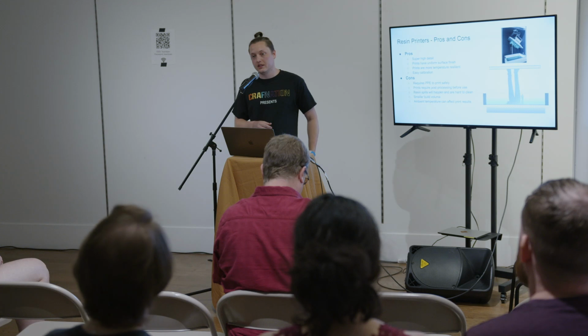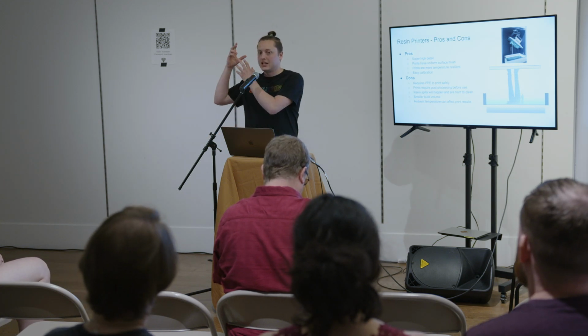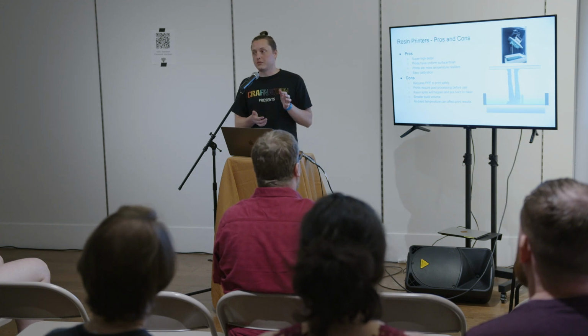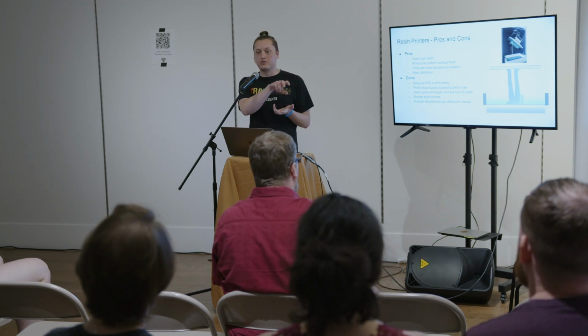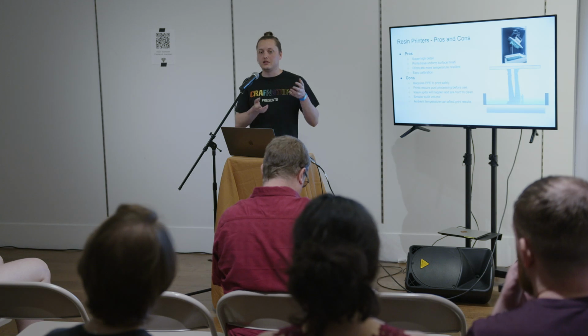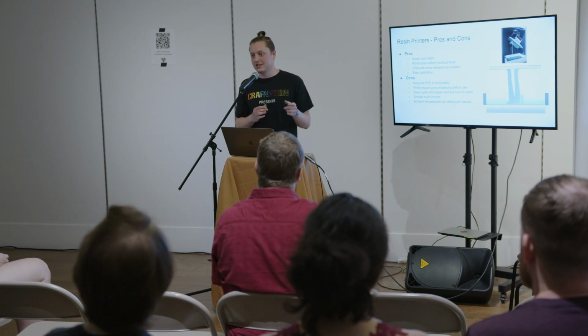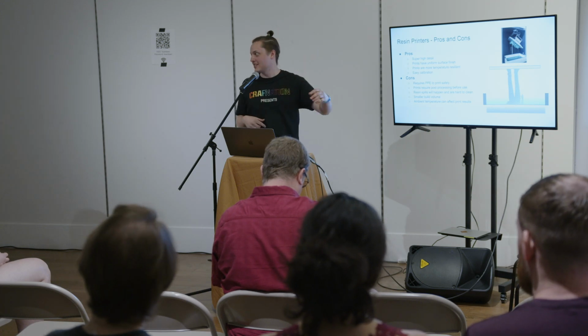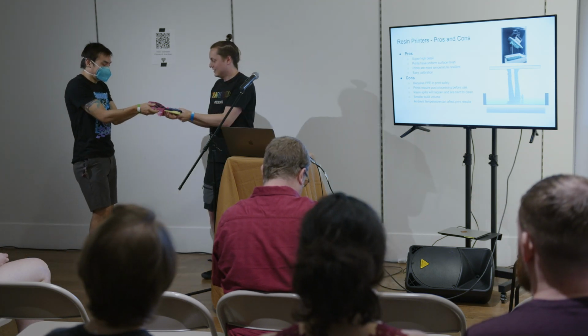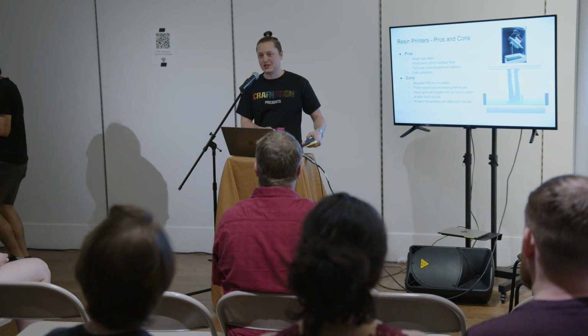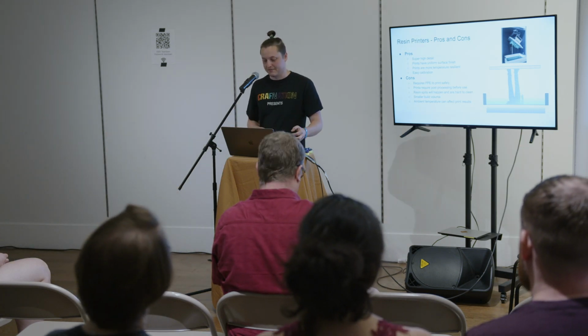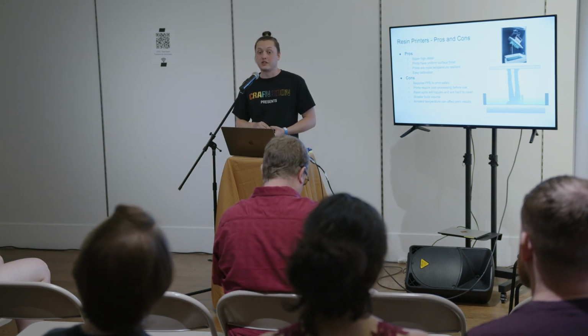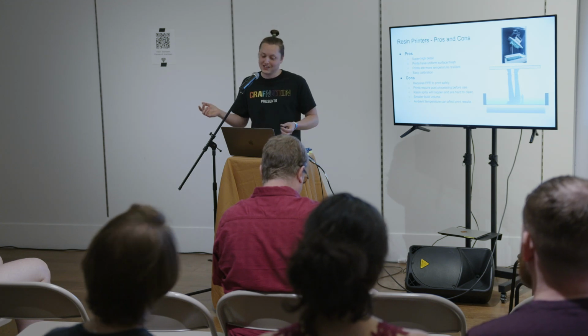Cons, you basically have to wear protective equipment to work with it. You have to do the post-processing, which is basically you take the print off. Usually you need to use something like isopropyl alcohol to wash the print, and then you put it into a station that has UV light curing, with a little spinning disc and lights that finish curing everything at the end. Again, the build volume is usually way smaller than FDM, but you get the super high details.